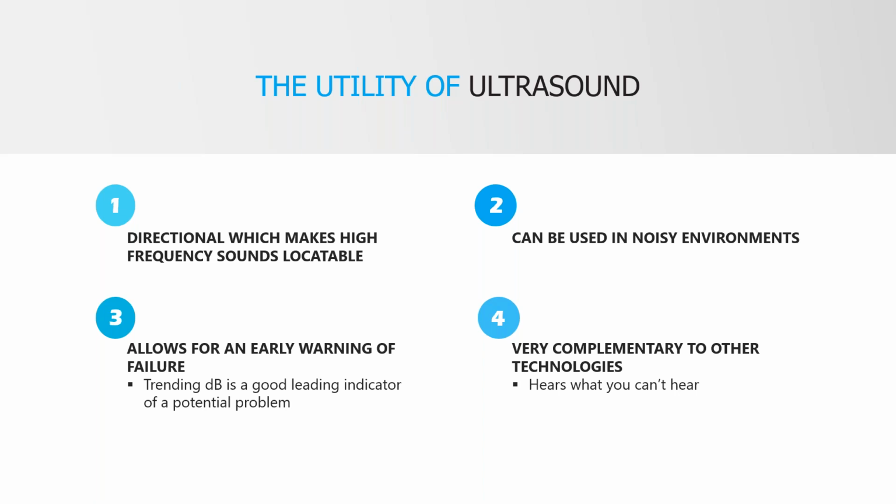And all of our instruments are going to have a sensitivity adjustment. So when we get into compressed air and compressed gas leak detection, we'll talk more about that. But again, because we're listening for these high frequency sounds, ultrasound is very directional, meaning that it's very easy to pinpoint the exact source of where that sound is coming from. And again, in most cases, we don't have to be too concerned about plant ambient background noises.